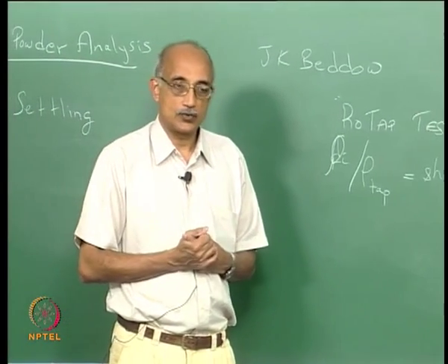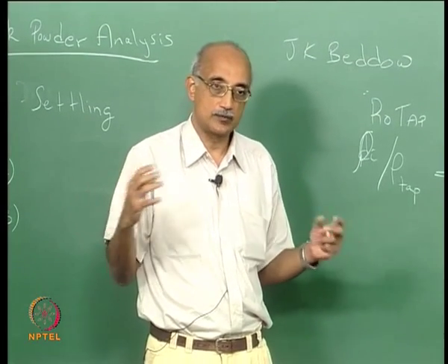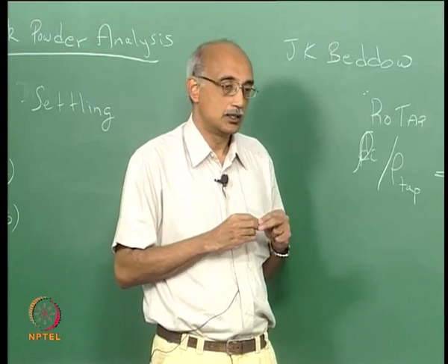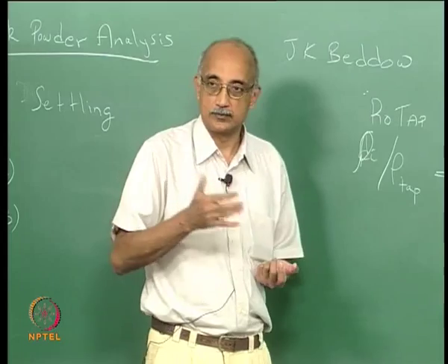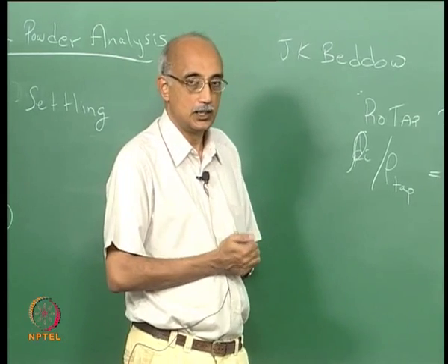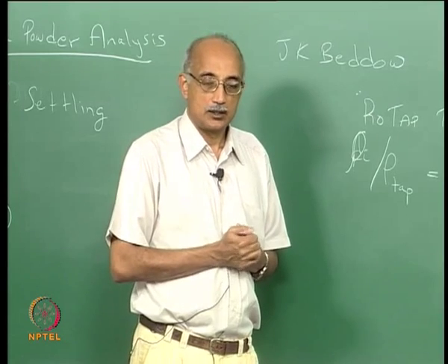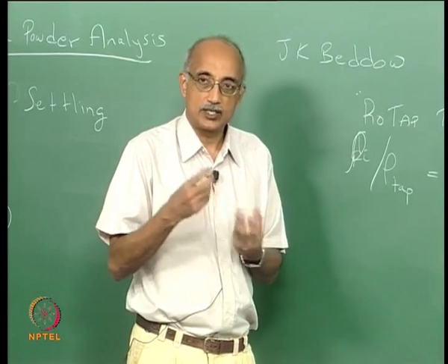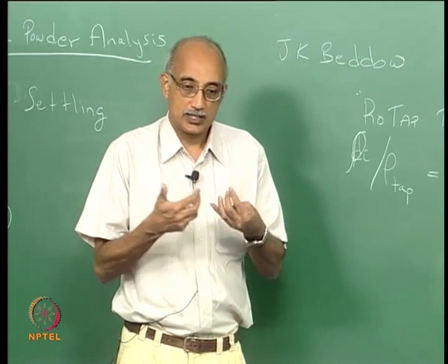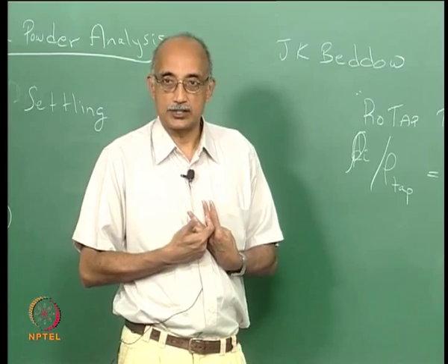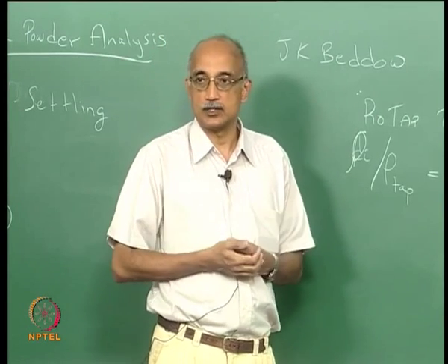On the other hand, if you have a powder in which the particles have varying shapes ranging from highly spherical to highly elliptical, and if you have a highly non-uniform distribution of shapes in the powder, the settling is not going to happen easily, because if you have two particles side by side and one is spherical in nature and the other is needle like, actually the surface area of contact between the particles is minimal, and that alone, as we will see later, prevents cohesive behavior.